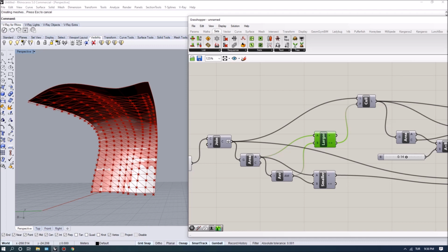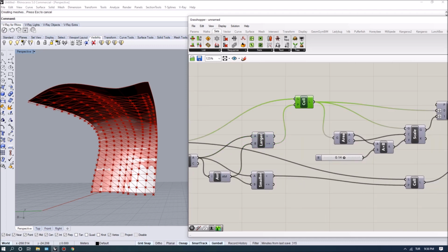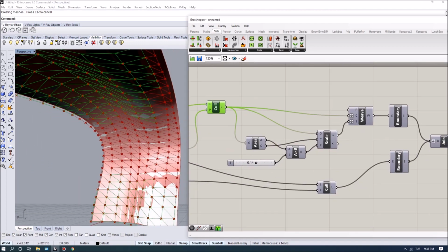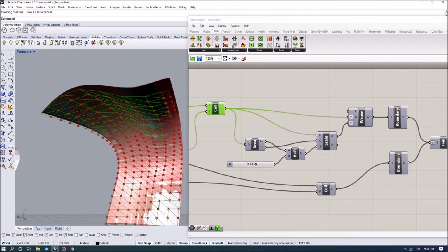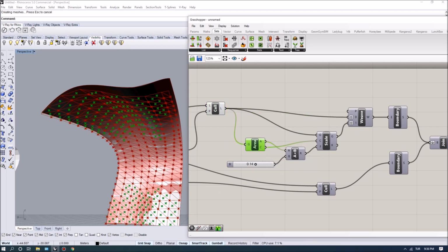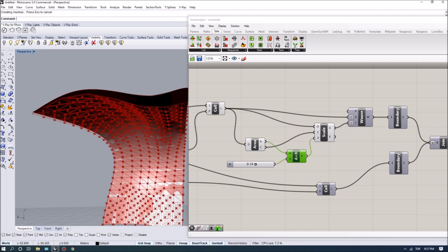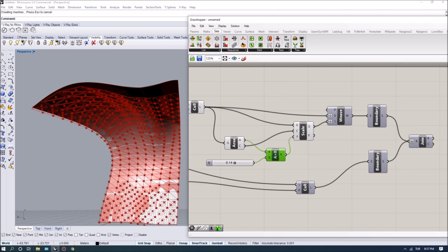This goes into the pattern, and we supply the lists, and we can find the larger panels in our configuration. Then for each larger panel, I found the centroids and scaled down the boundary condition on the centers, using the area with some multiplication. You can also give any type of percentage here, it would also do the job, so you don't have to use the area. If you supply 0.9, they will all be uniformly scaled down.